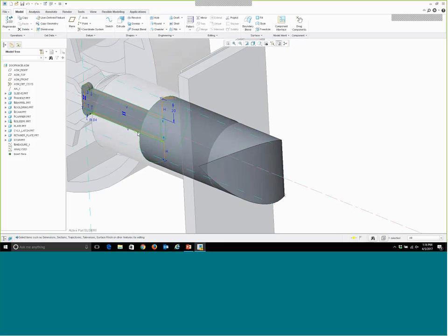So we have this 0.875 dimension. That dimension will be increased or decreased, which will move the flat part of this cylinder to adjust so that we maintain that minimum of 0.2 between the flat here and this stop part back here.